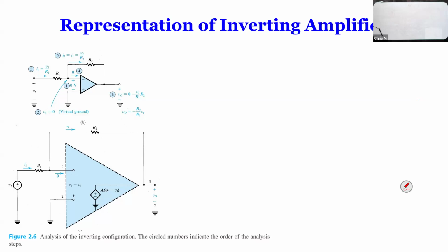So if this is grounded and this is a virtual ground, they call it virtual ground because it is not actually grounded, but the voltage is 0 because of the infinity gain, right? And now you see here, V1 minus V2, minus V1, is 0. So A times 0 is infinity. Therefore, they give you some sort of fixed voltage. You cannot calculate from this equation, but you actually have to calculate from the feedback. Right. So we're not going to go into too much detail over here.